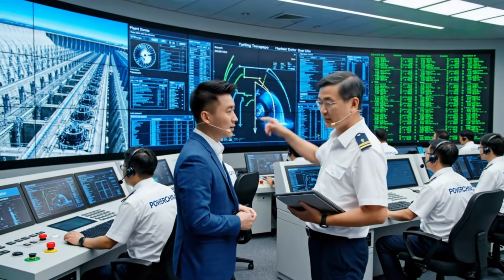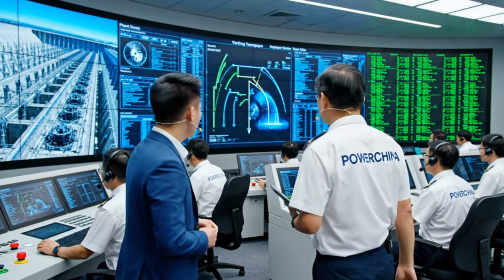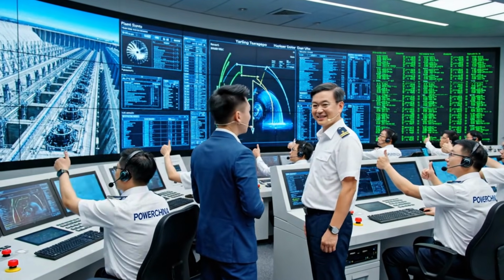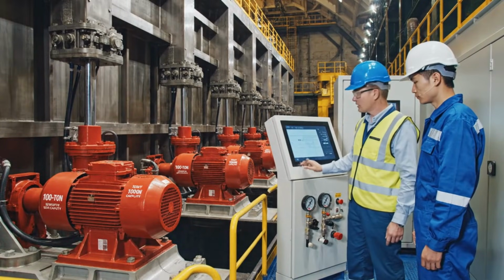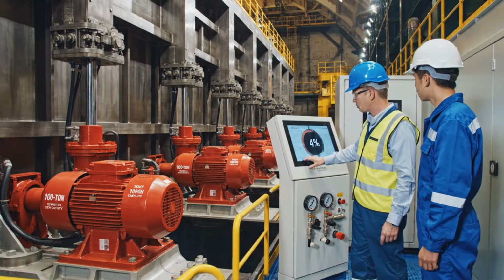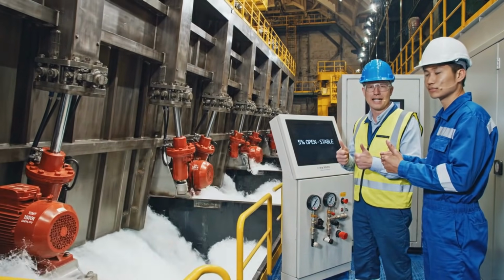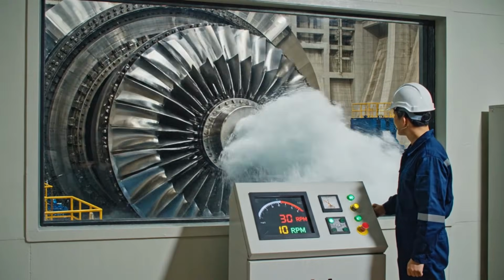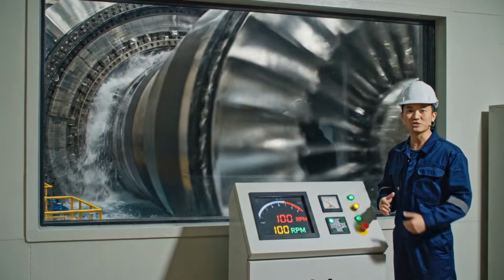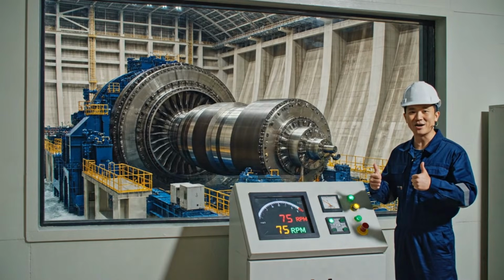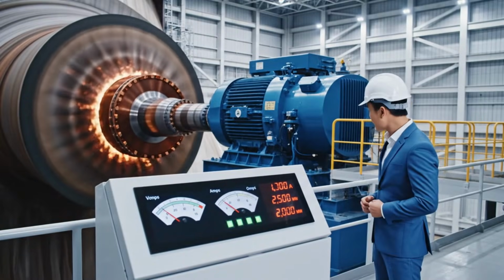He's ready to ride. Turbine status optimal, generator conditions stable, 8 years of work culminating in this moment. Truly impressive. These 100-ton hydraulic servo motors operate at 250 bar to precisely control the 24 wicket gates. The massive runner accelerates towards synchronous speed, and there it is, 75 RPM.